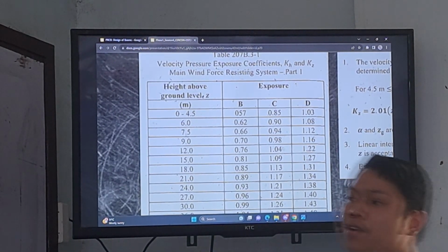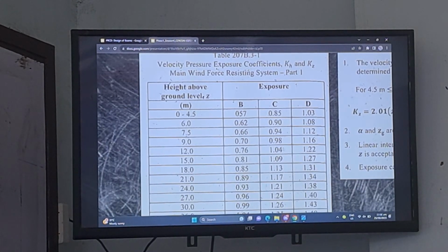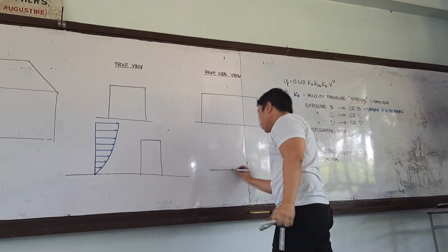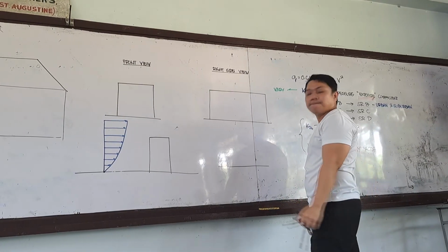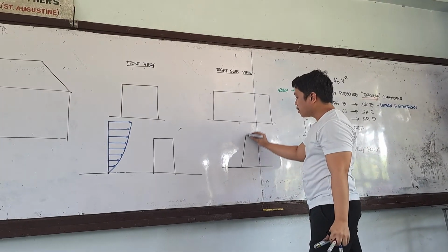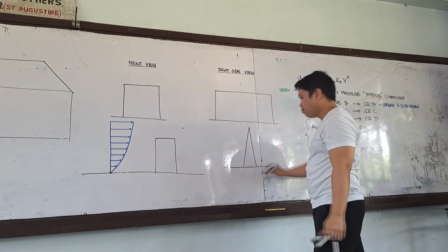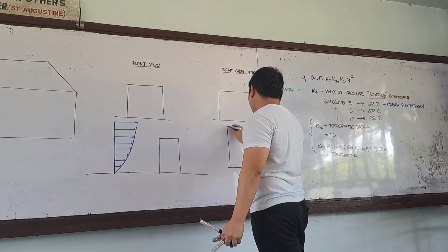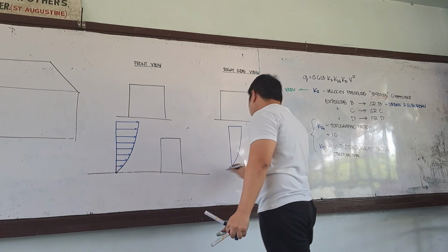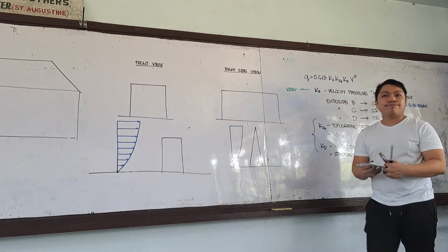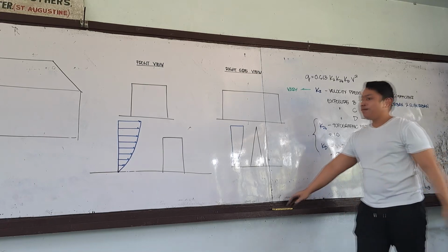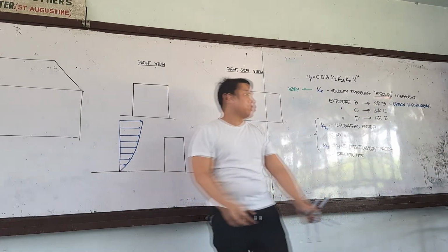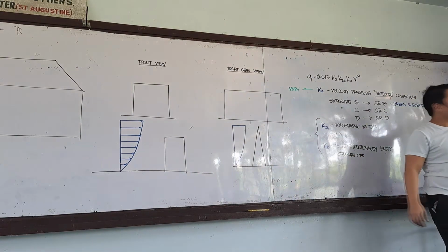The design for high-rise structures. Notice the shape of the Burj Khalifa? It varies, right? That's why our wind pressure is greater at the top compared to the bottom. So we can quantify this increase of wind pressure in our Kz.